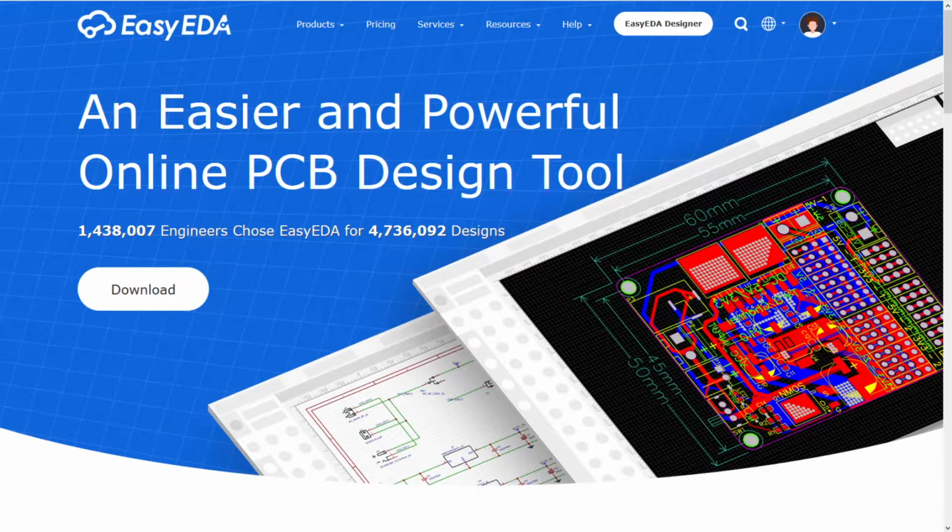I can share a link directly to Easy EDA of the project that will have the schematic and the PCB designs on it that you could then open up in your browser and play around with just to get a feel for things. If you create an Easy EDA account, which is free, you can then save that project to your own account, modify it however you want, and have Easy EDA generate the PCB design files for you that you can then upload yourself to OSH Park or some other company that will manufacture PCBs. So that's why I'm going to go with Easy EDA.